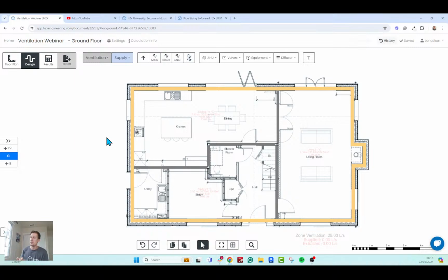All right, well, let's start doing the design. There's only a few parts to this. First, you want to make sure you're on the right system when you're drawing it. And these are all the ductwork drawing. So if you remember back to the flow system settings, where we had different settings for the mains, the branches, and the connections and risers, you can control all of that here.